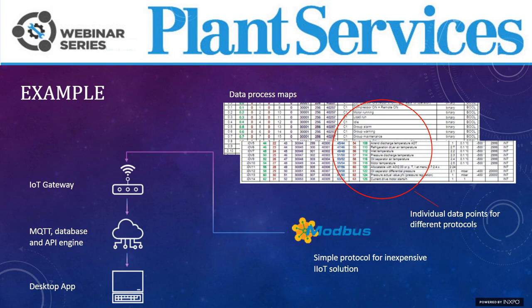So here's an example for a low-cost IoT solution, and it's a very generic overview. However, certainly sufficient if you are interested in just a limited amount of data. Let's go through this example here. So we have on our right a data process map. You would eventually select your important data points. And I selected Modbus TCP. Modbus itself is a very simple, lightweight protocol. There are a lot of free tools available to implement Modbus TCP.